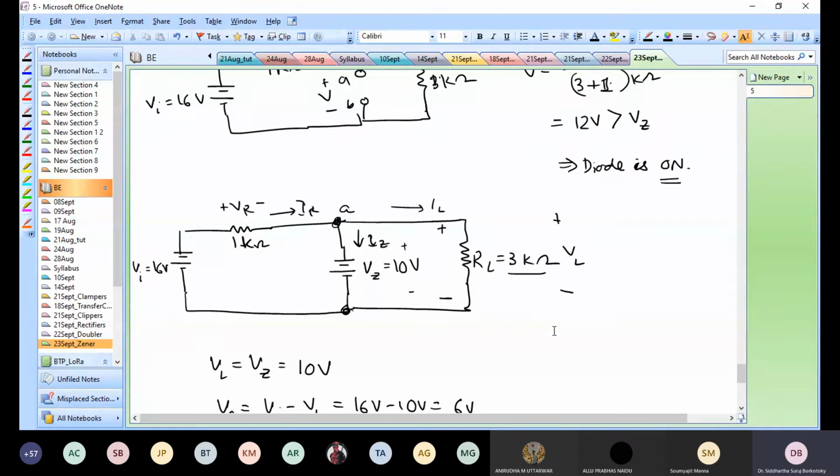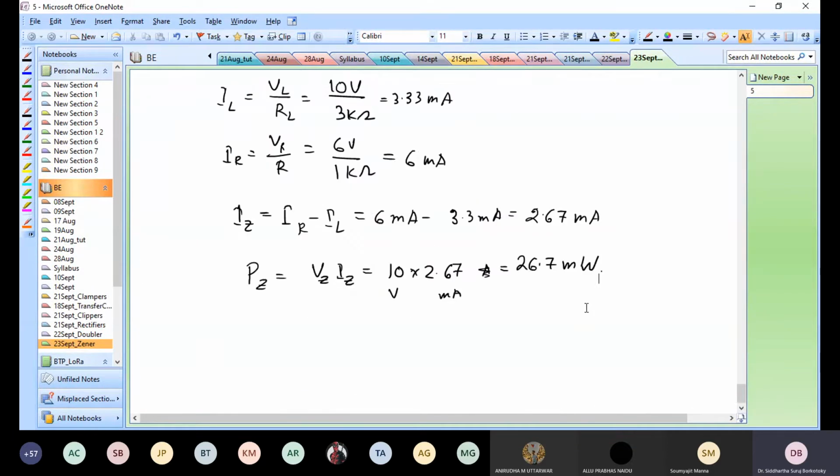If the voltage goes down to some small value, then at some point the diode will stop conducting, and you will get some voltage other than 10 volts. So that's another matter. When we are designing a circuit, we have to be careful about these things. We have to specify that to this circuit apply a voltage of this many volts or higher. To this circuit connect a load of this many kilo ohms or higher or lower. In this case, it will always be higher. So always ensure that your minimum load resistance is this. That is what we have to be careful about.